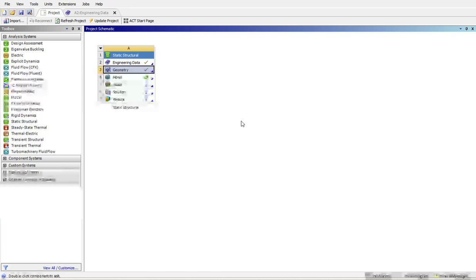The file that we've been provided is a .ipt file. I have not found a way to open those in Workbench with the version of Workbench and Inventor that you can download as the student versions. So what I've done instead is I've just gone into Inventor and exported that file as a CAD file, in STEP format or .stp, and that'll allow you to play around with that in ANSYS.